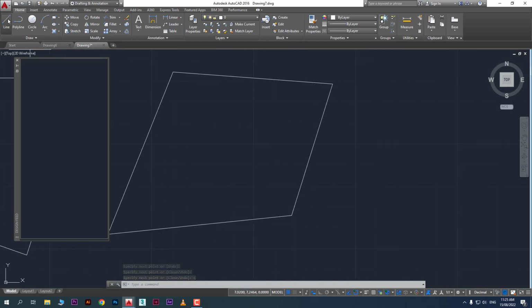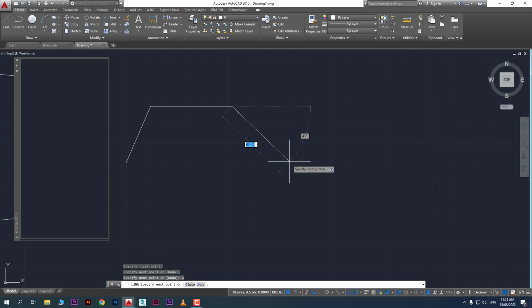When you are taking a line, you can see it's giving you the options to put the values near the cursor. Like you can see 1.44 is actually the length of the line. Now it's showing you the length of the line is 1.7992 units. If you want to put a value directly near the cursor, you can put 2 units, then enter, then the length of this line is 2 units. So this is called dynamic input.